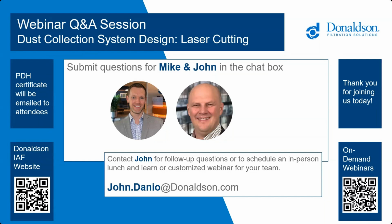So, if you know that a customer has, for example, a 20 kilowatt laser that they want, and they're always going to be cutting, let's say, half-inch thick material, and they're running 24/7 versus 8-hour shifts, you're definitely going to want to size the AMR more conservatively. So think of the thicker the material, the more they're cutting, the more media you're going to want to have present on the system.